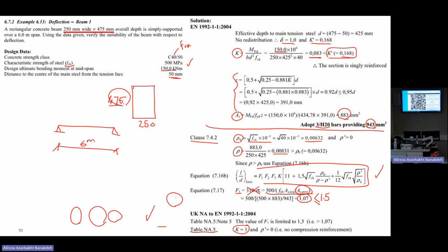Alteration. But if the difference is too much, you probably really need to increase the H, the height of the section. There is no other way. Or use a better concrete, a higher strength concrete.